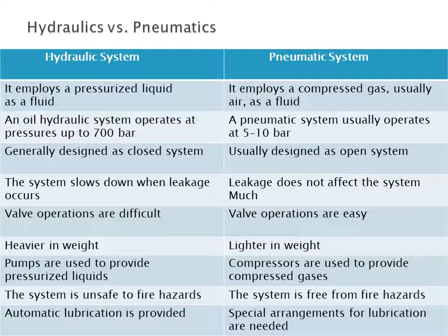As I told you, in the case of hydraulic system, a high pressure is developed, up to say for example 700 bar, whereas the pneumatic system works under low pressure, say 5 to 10 bar. So you can see in comparison that the design of pneumatic system and hydraulic system are totally different.